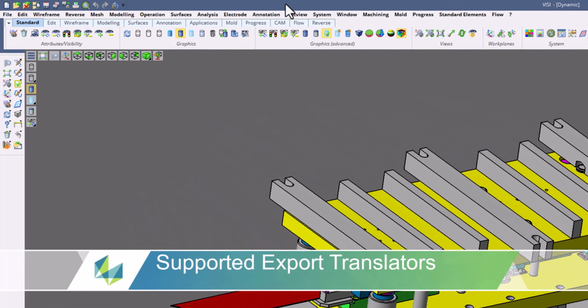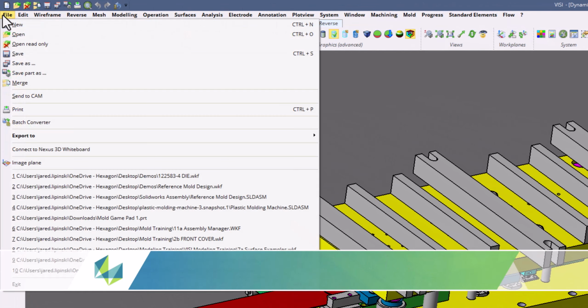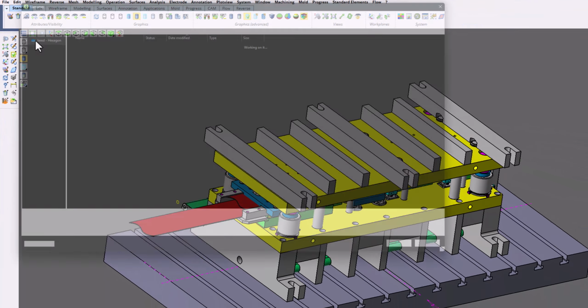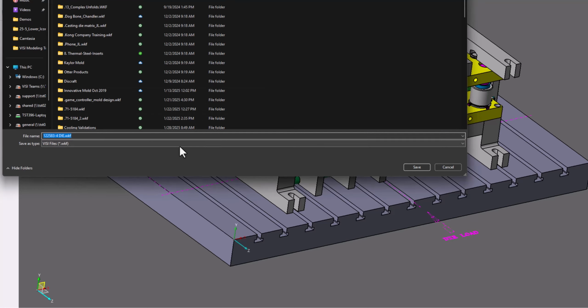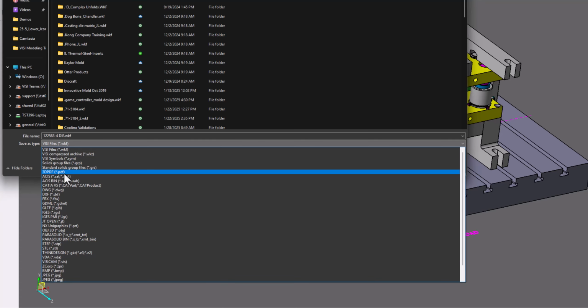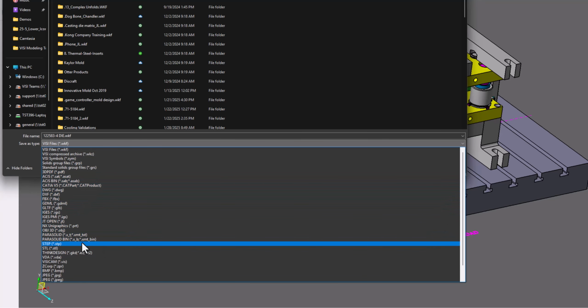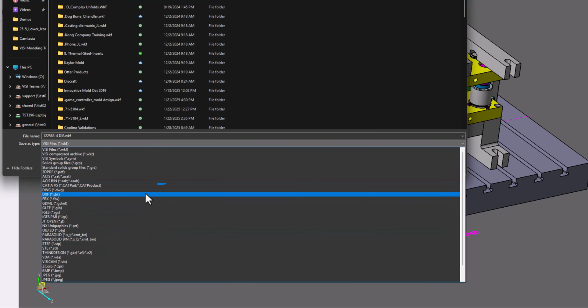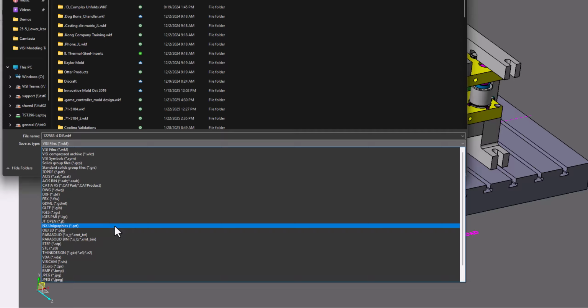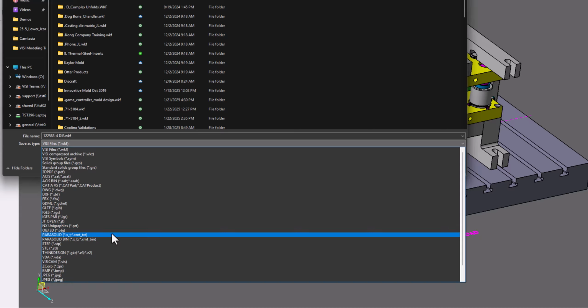Once the assembly tree is created from the assembly view, we will now review exporting the tree out for other programs to import. In our example, we're going to export as a 3D PDF, as well as a step file. Please note that the way we are exporting is the same in other translators. VISI also offers a wide range of export translations as well, such as CATIA, NX, Parasolid, and other general translators as well.